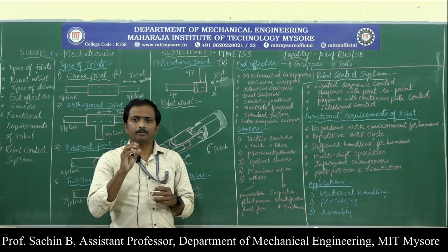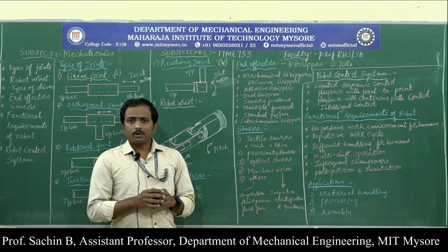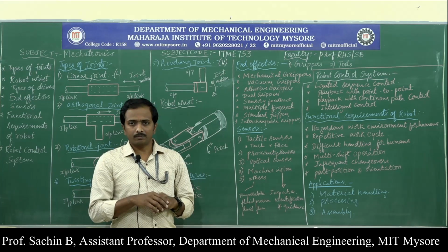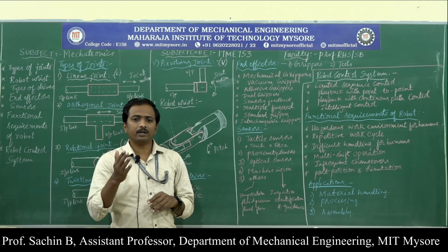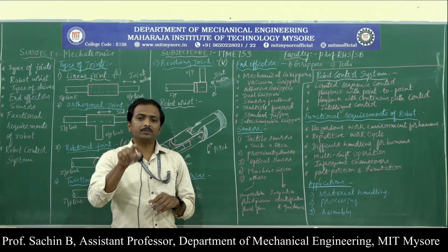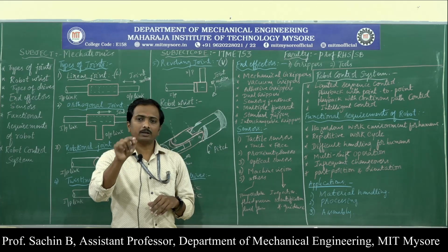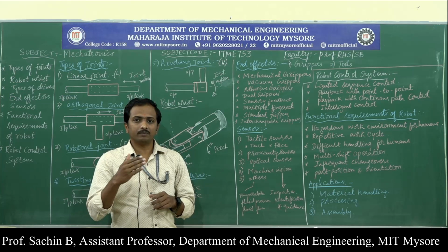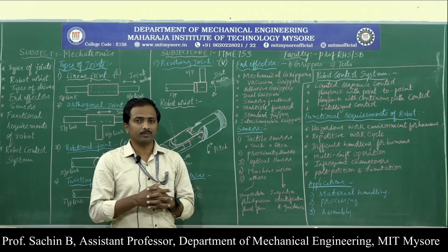A beam of light will impinge from the transmitter and pass to the object, while the reflector or some other structure material is kept behind the object. The transmitted light will pass to the object, and that light will again come back to the receiver. By knowing that, we can tell whether it is a surface-finished object or a metal or any other type of material.